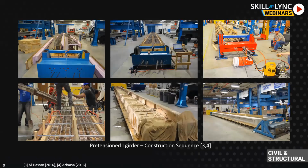Let's look at the prestress through pictures. On the top left, before we cast, we have the skeleton ready, though you don't see the formwork there. We lay our strands, we lay our skeleton of the structure the way we want, and then we erect the formwork. Then in the top middle, you see there are some anchors right here, and these are connected. You can also see a computer connected to a load cell so that we can monitor the load. The picture you see is from a precast bed. We call it a precast bed.